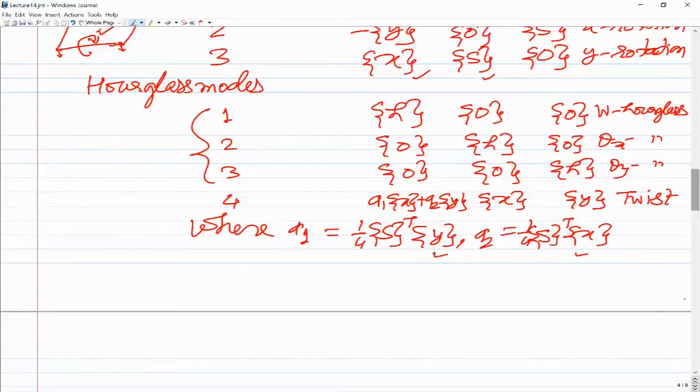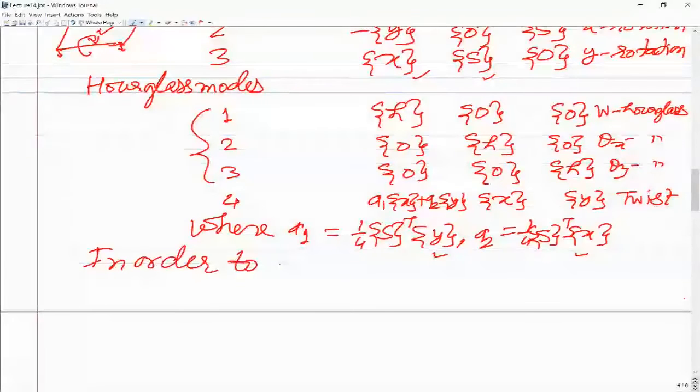If you use this reduced integration element for thick problems, these hourglass modes would be activated, and if they are activated, if you look at the deformed shape of the mesh, you will see that it would be kind of zigzag. Alternately, the nodes will have positive and negative displacements and rotations. So we need to control that, which means we'll have to add an additional stabilization matrix so that these modes are not activated. In order to control the hourglass modes,